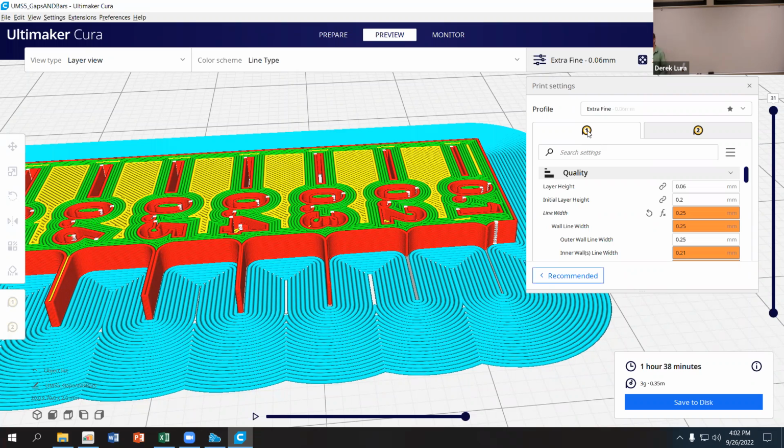Usually the biggest change from going from one material to another is the printing temperature, and whether or not you need to use supports and build plate adhesion. So PLA is pretty nice because it doesn't contract too much as it cools and melts at a fairly low temperature.